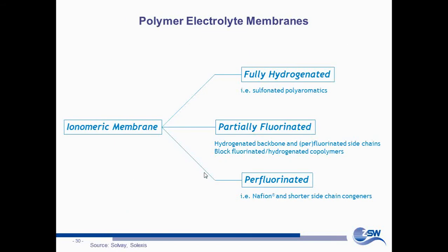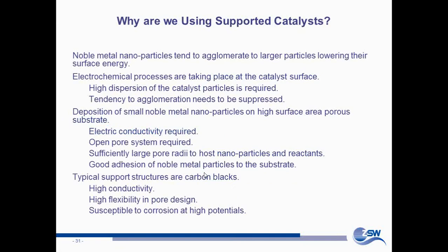So the polymer electrolyte membranes, we've got about, for the low temperature PEM fuel cells, about 3 different kinds. One that's fluorine free, one that's partially fluorinated, one that's to a certain extent perfluorinated, and I will leave out all these beautiful composite membranes based on polybenzimidazole and phosphoric acid, since that would take forever in the day if we covered these here as well.